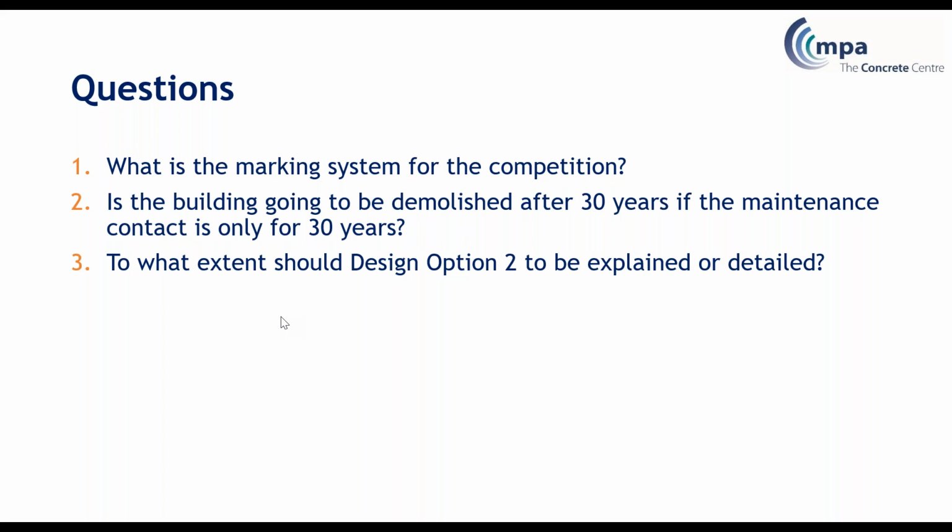So you don't need to do a full design, just a conceptual design, where the sizing is reasonable and you've made sure the stability is correct. So you've got a stable system, you've taken those horizontal loads and those vertical loads, and you've got them all down to the ground in a reasonable way. The foundations are reasonable. So that's the extent.